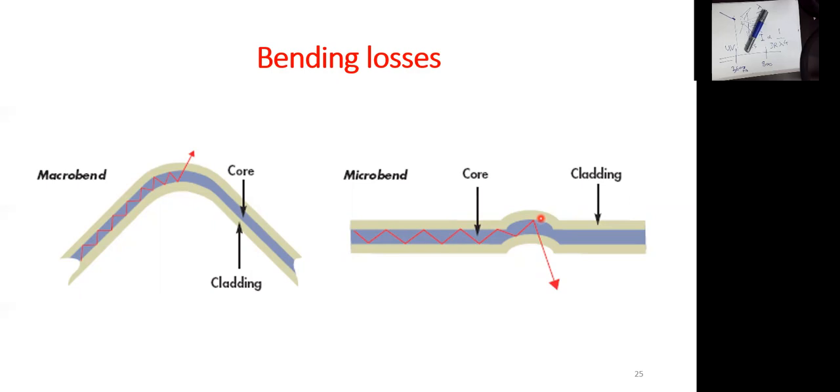there is a microbending. On the other hand, due to different logistics and dimensions, sometimes we need to make this optical fiber somehow in a curved manner. Not all the time will it be fixed straight. And this case is what's called the macrobending. Accordingly, of course, as you can see, bending can cause losses because you change the angles or you change the borders, so losses can appear like this and this.